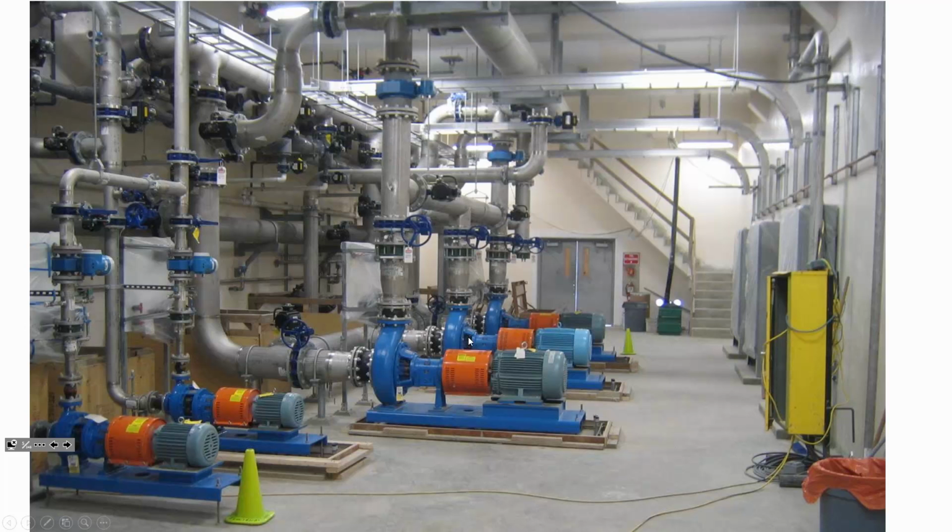And that's one of the most challenging environments for calculating hydraulics, because they really prefer that the water pass through either a sewer plant or a water treatment plant under gravity flow. You know, they'll have some pumps because they got to lift the water out of the sand filters and put it onto the next step. But besides that, out of the sand filter, they're trying to have the water move from place to place just by gravity to save electricity. And so, when we look at some energy grade line and hydraulic grade line diagrams through the semester, some of the most intricate, detailed, and careful calculations are in water treatment plants like this.